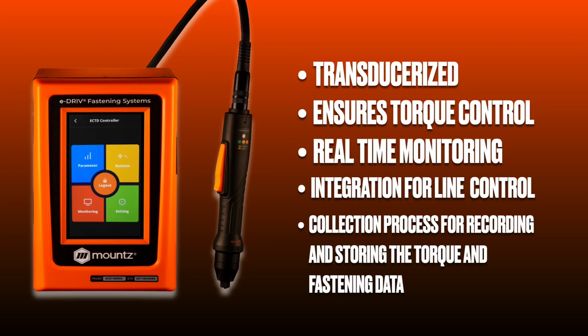All give you the ability to monitor what happens with the tool in real time. Again, so we can help to notify the operator when there is an error, and they can go ahead and make that correction at that point. These types of tools do offer integration for line control, whether it be a PLC or if it's in communication with an MES system. That is available here. And the process for recording and storing the torque data is available as well. And we'll touch on that here in just a second as well.